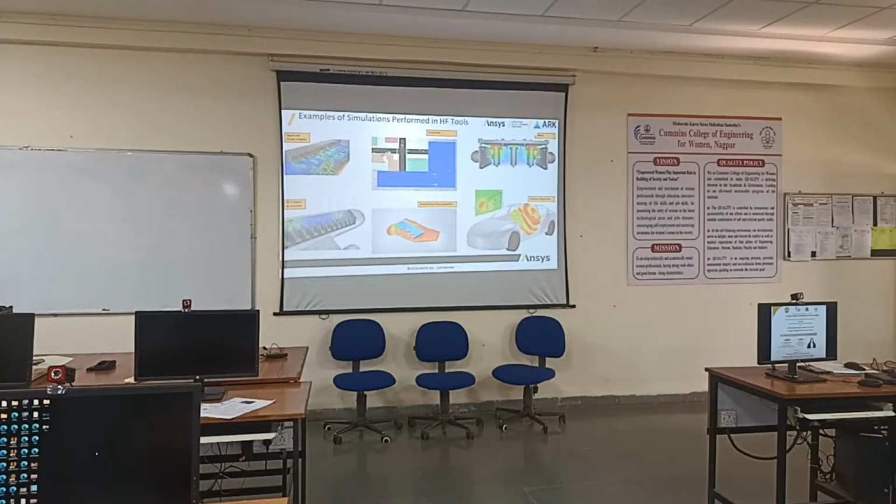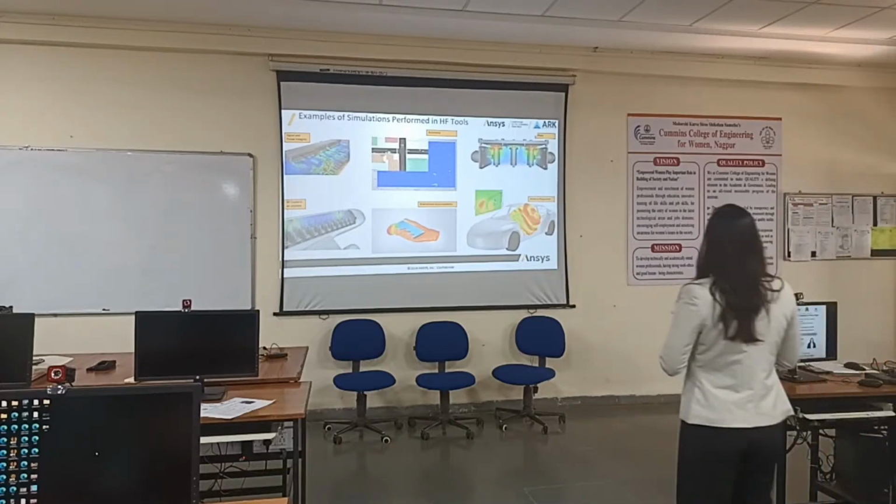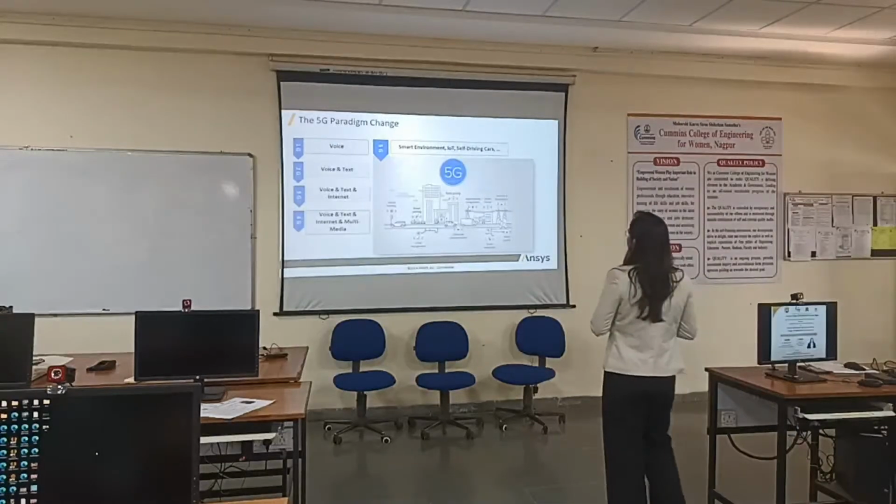And the next one is antenna placement. You can see this is a car CAD model. In the left rear of the car, I have placed a PIFA antenna. And for that antenna, how the gain and radiation patterns are getting changed, if you put it on some particular object, how the radiation pattern, E plane, H plane are changing, that kind of analysis we can see here. This is one example where the SBR plus solver is useful. This is for antenna placement.